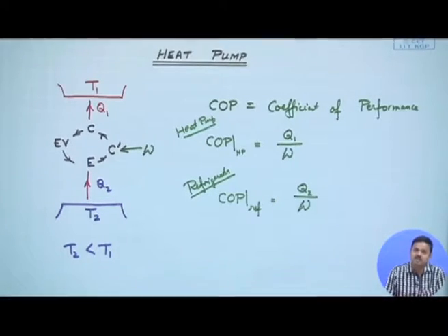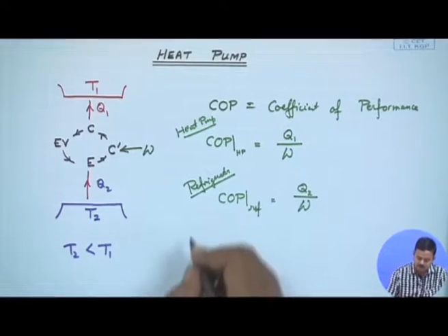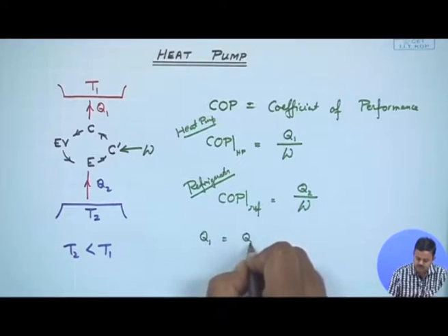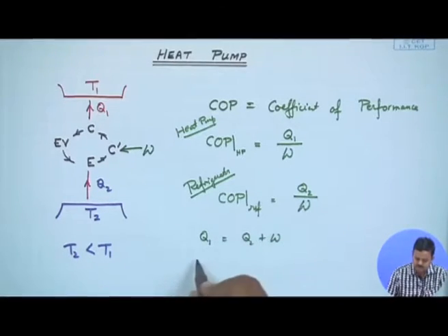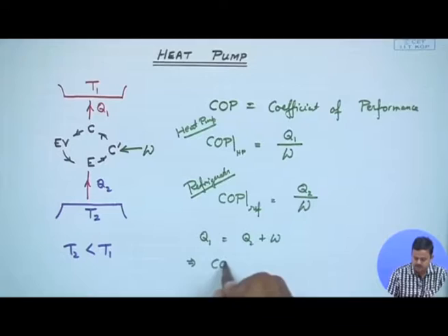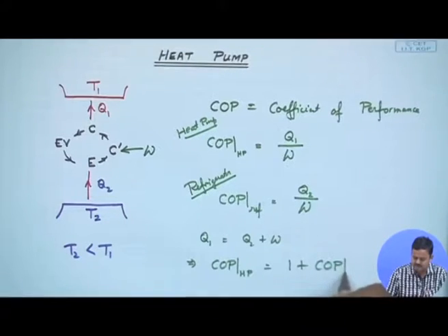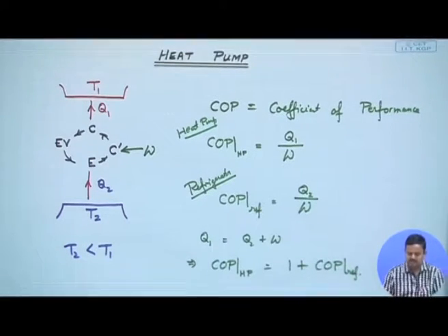Now, from the first law of thermodynamics, since Q1 is equal to Q2 plus W, I can show that the COP of a heat pump is 1 plus the COP of a refrigerator.